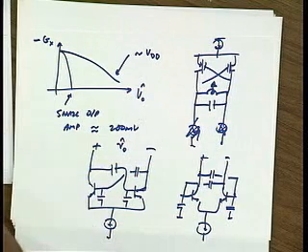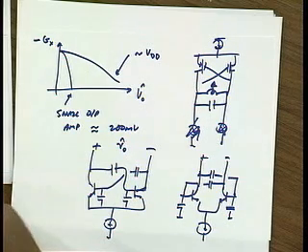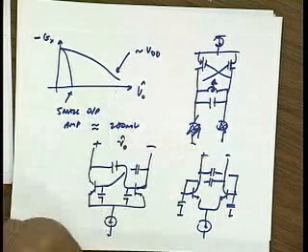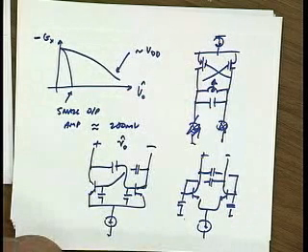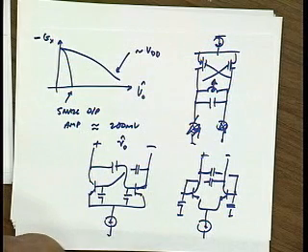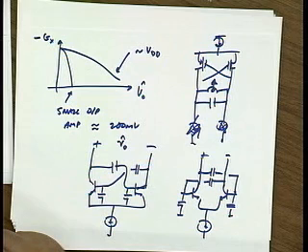Okay? Won't you also be more linear if you don't put a current source? The overall transfer function of this cell would be more linear. Yeah, and that's exactly why you end up going to VDD, right? It's the triode region that ends up limiting you. Yeah, but remember, linearity doesn't really matter so much for an oscillator, right? I'm sorry? Yeah.